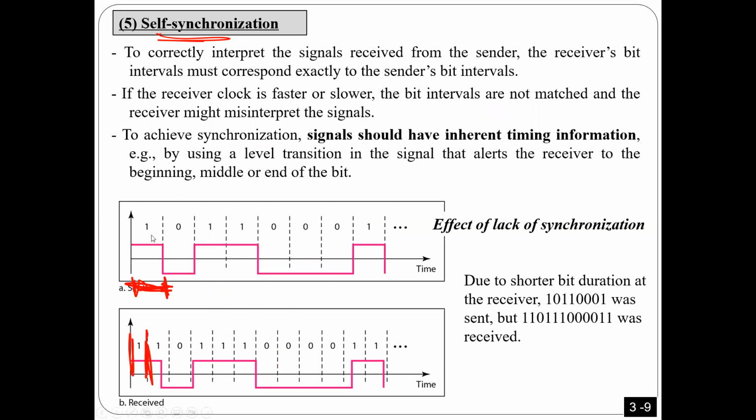So what happens, you transmitted 1011 0001, but I'm going to receive different data. When you transmit this one here, although you transmit only one bit, which is 1, as a receiver I'm going to interpret it differently because my boundary is here.